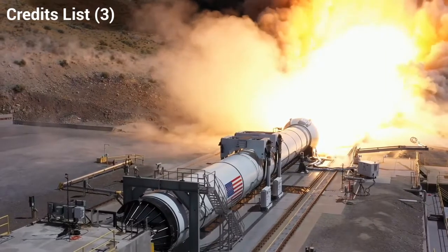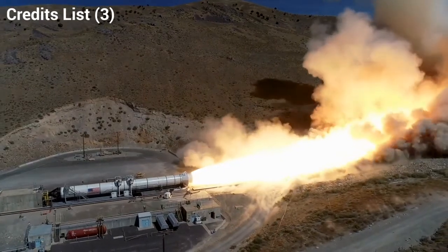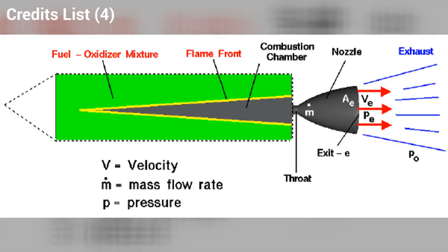The alternative solution would be to use solid fuel rocket boosters as they are cheaper, more energy dense, and easier to refurbish. However, solid fuel rockets have their fuel and oxidizer premixed and therefore cannot be throttled, which would make propulsively landing them impossible until now.